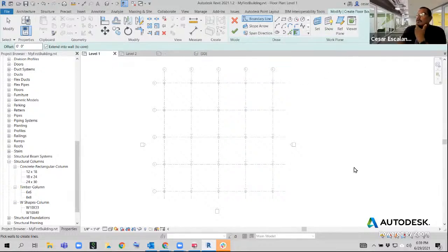All right, in this mode, all you can do is sketch lines, and sketch lines are these purple lines that define the boundary of an object. And so I want to create the boundary of my ground level, or my ground floor, 2 feet away from the grid intersection. So I'm going to use the line tool, the first option here.